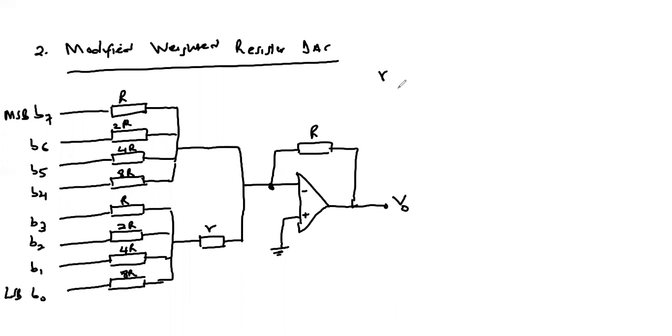We can analyze the operation of this DAC and determine the value of the resistor small r as follows. If we let bit 3 be 1 and all the other bits be 0, and we analyze the second stage of the DAC, then we can have the following circuit.